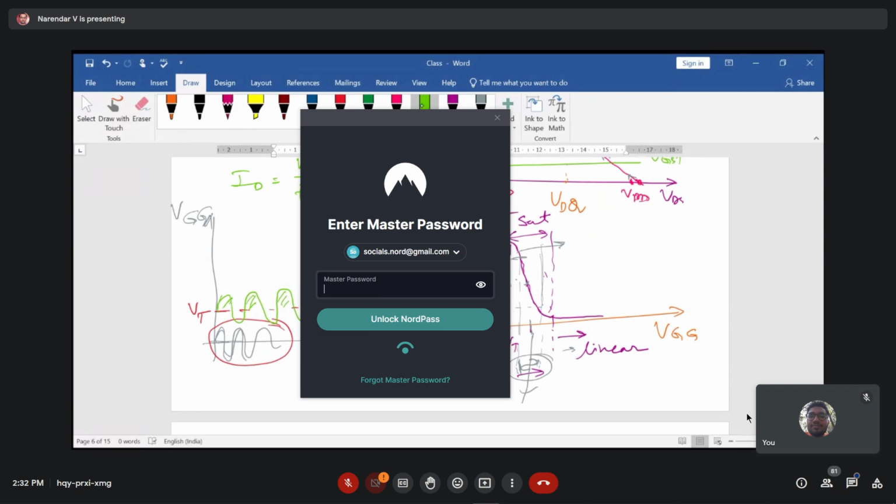So what you have to do is keep it always well above the VT value, and fix the value of VG here. This is your VGG or VG value. It is well above the VT value, so that maximum amplification can take place in your circuitry. Here, if it goes this way, now the transistor recognizes both the positive peak and the negative peak of your small signal, which is getting amplified.